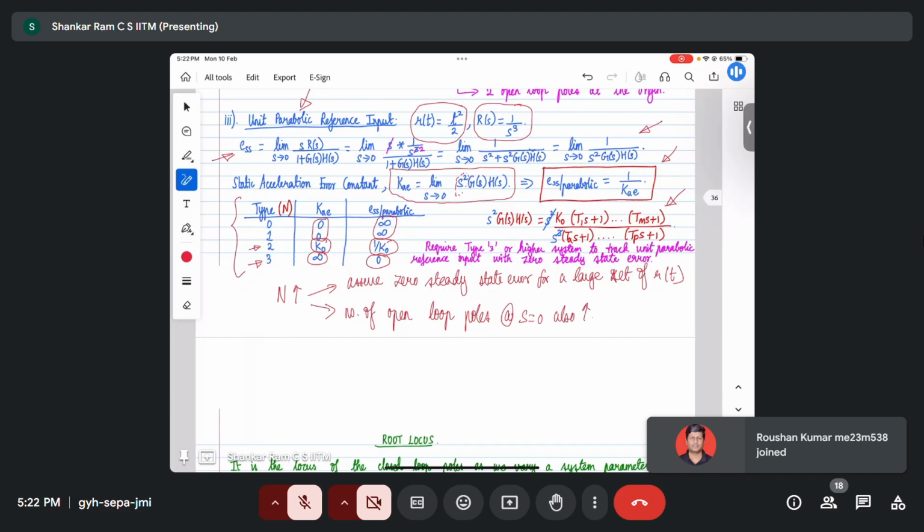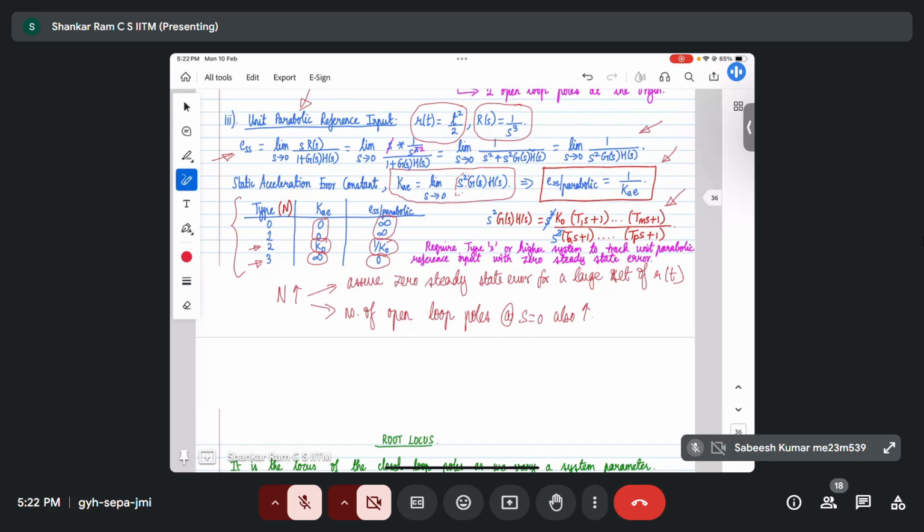So you and I are not really looking at zero steady state error for a ramp or a parabola from a practical perspective, right? I'm just giving an intuitive answer. From a practitioner perspective, by and large, most likely we want to keep some variable constant for an extended period of time. So that is why guaranteeing a type 1 system is by and large sufficient. That is why I'm using all these terms very carefully. I'm saying typically, by and large, from a practitioner's perspective.